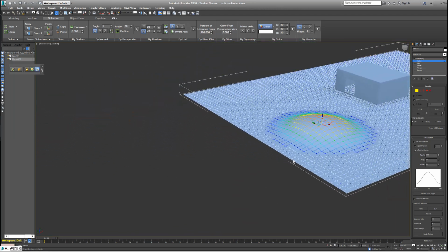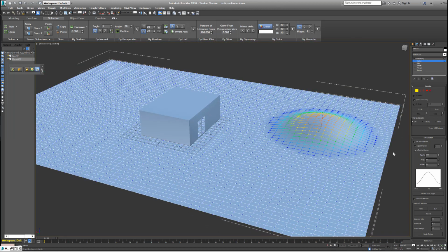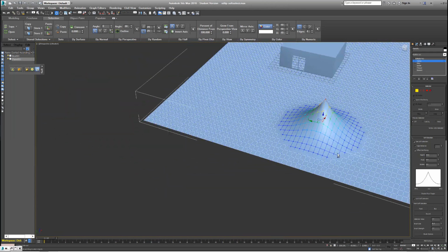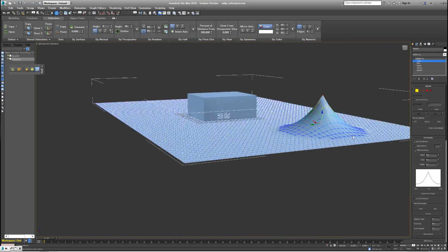That's exactly what I want. So this is the falloff. If I just hit Control Z a bit, the amount of pinch, just to show you that again, if I increase this, it's actually centering. If I just hit W again, I've increased my pinch amount. It's making more of a peak. It's centering that magnet along only one unit, and it sort of weakens as it goes out. So you're going to get more mountain-like effects.